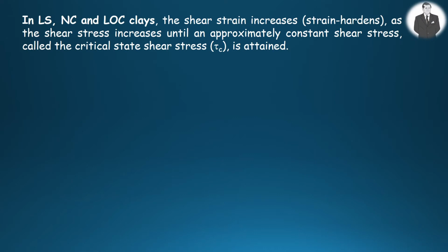In loose sand, normally consolidated and lightly over-consolidated clays, the shear strain increases as the shear stress increases until about constant shear stress, which is called the critical state shear stress, is obtained.